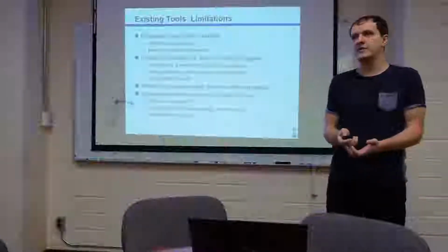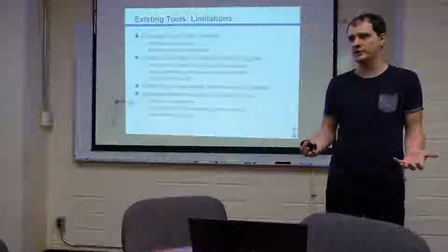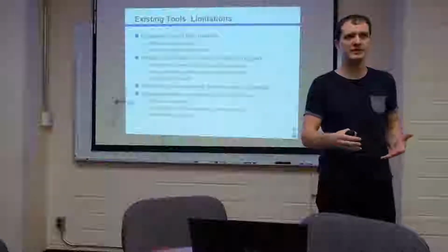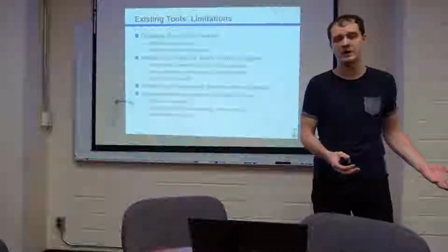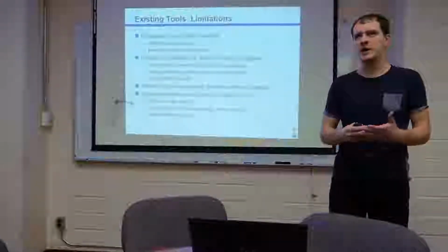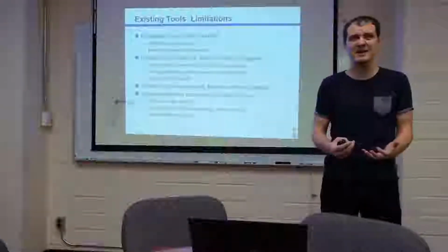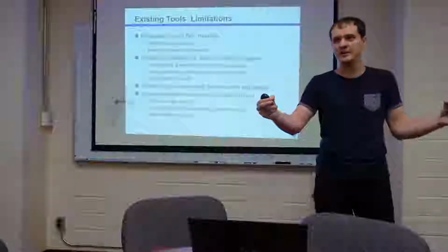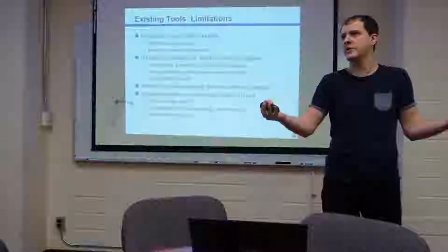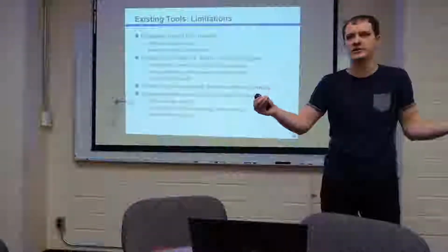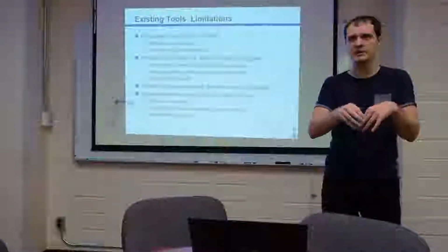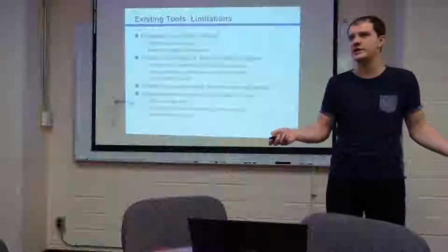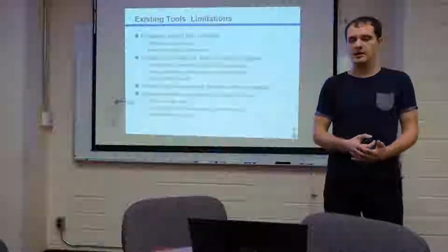So besides memory maps, streaming protocols are also supported by these tools, and these are point-to-point connections that are lower level and make fewer assumptions about the communications than memory map does. But they come with a low level of automation. What I mean by that is when you specify that streaming link, nothing much is done by the tool. It's just a point-to-point connection with wires is what you get. You don't get any ability for the tool to instantiate interesting interconnect. So that's a trade-off that you have in this current world.